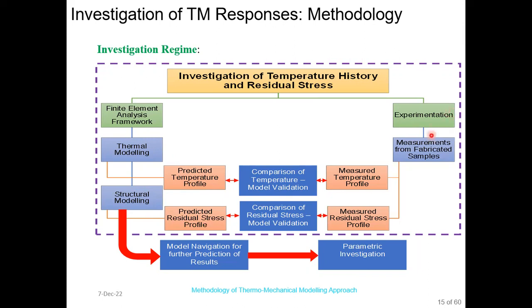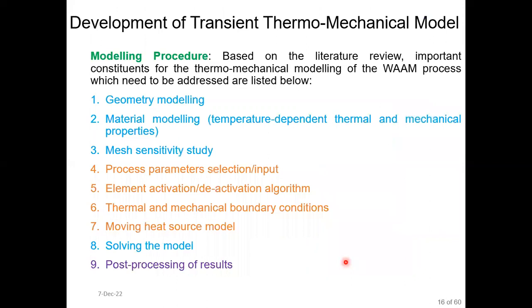Similarly, from the experimentation, I have measured the temperature profile during the deposition process and the residual stress values after the deposition process, and I have compared these two values, and after a satisfactory comparison, this model has been further utilized for parametric investigation.